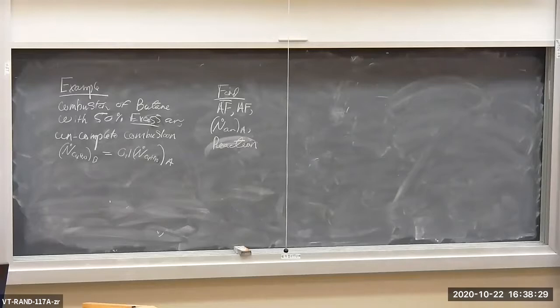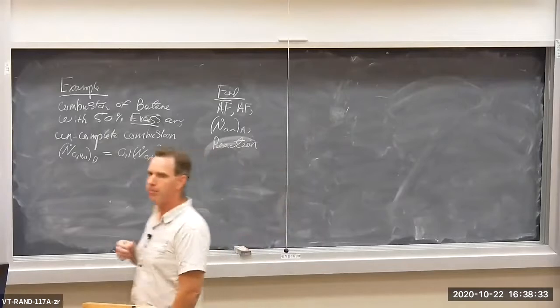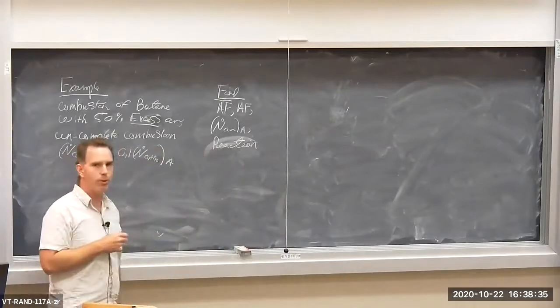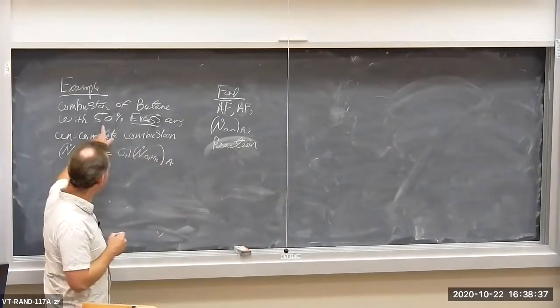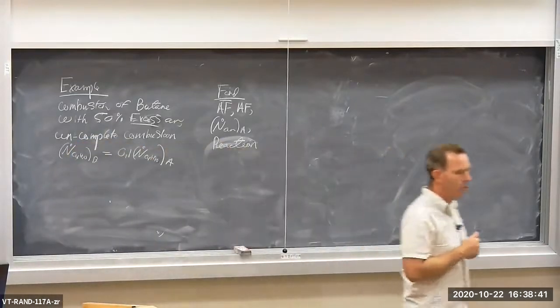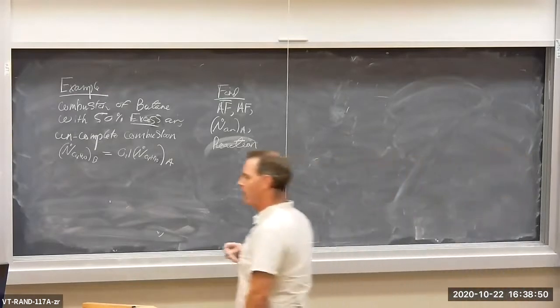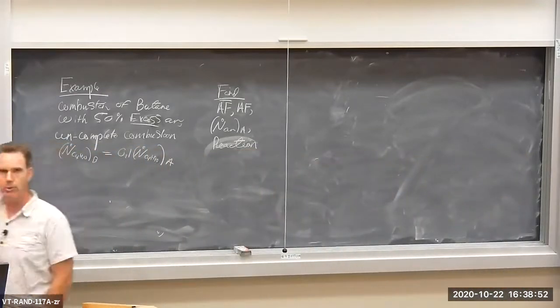We're going to take our results from the previous example, and we're going to recalculate mass flow rates and therefore the reaction for 50% excess air. We're going to set lambda equal to 1.5, 50% excess air. In addition to that, combustion is not complete. Not all the fuel is burned. This is more realistic.